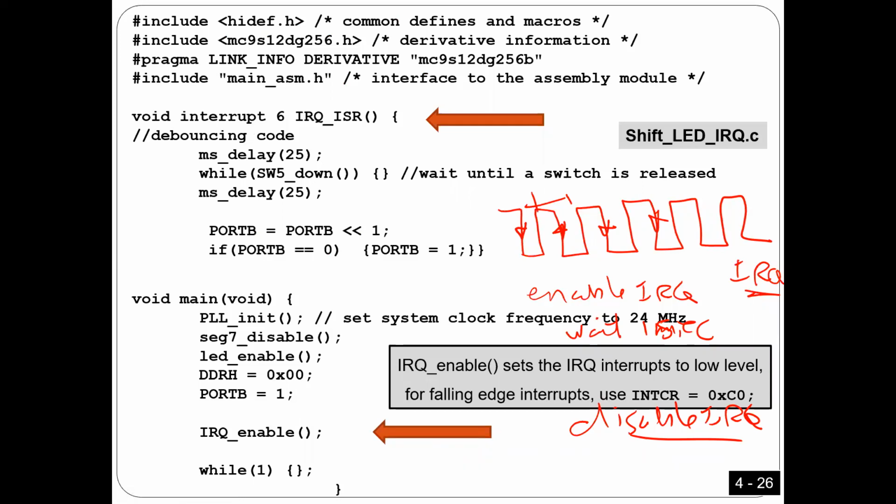Okay, so what is the definition of frequency? It is the number of cycles in 1 second, right? So the way I can use IRQ to measure frequency is I can take the signal and input it to IRQ, and this way I am sure IRQ is interrupted every 1 cycle. Is that okay? Then all I have to do is count how many times IRQ is interrupted in 1 second, and this gives you the frequency. Okay, any questions?